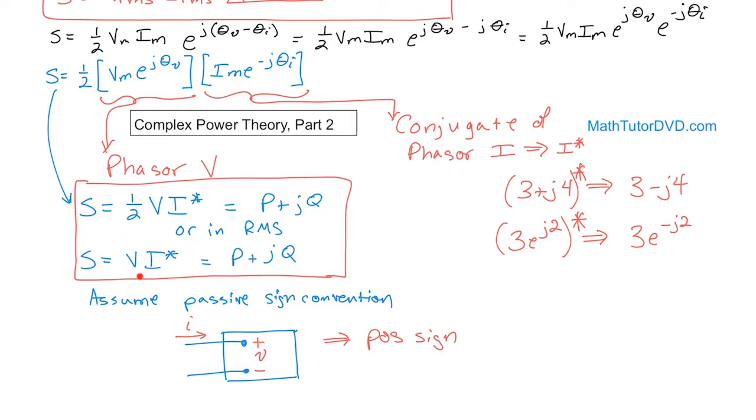The important thing to realize is that this equation here, it looks like P is equal to IV, or very similar to it from DC analysis. But this equation here applies to any circuit element that you would have with AC current and voltage going across it. So if you had a capacitor or an inductor or a resistor or any giant network that consists of all three of them, if you know the phasor voltage across that element, and you know the phasor current, take the conjugate, multiply it, then you're going to get the real and imaginary part.